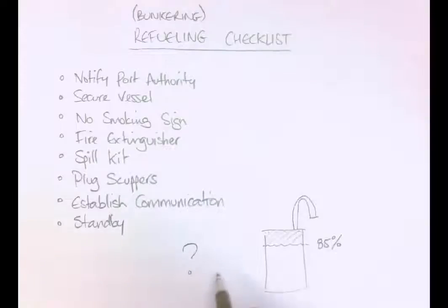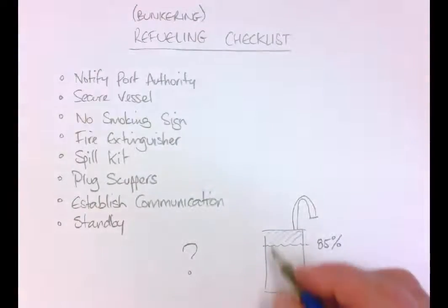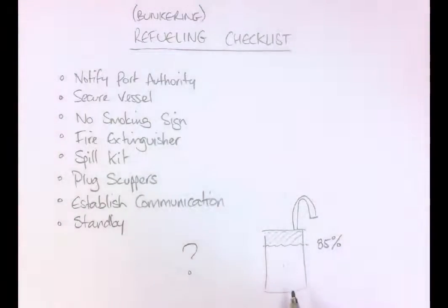We're going to be doing a lot in the pracs on how we measure the tank volumes, particularly with larger vessels that we're dealing with. We'll be doing a prac on bluefin where we've got to do soundings and use tank tables to determine what level there is in the tank and where we need to stop.